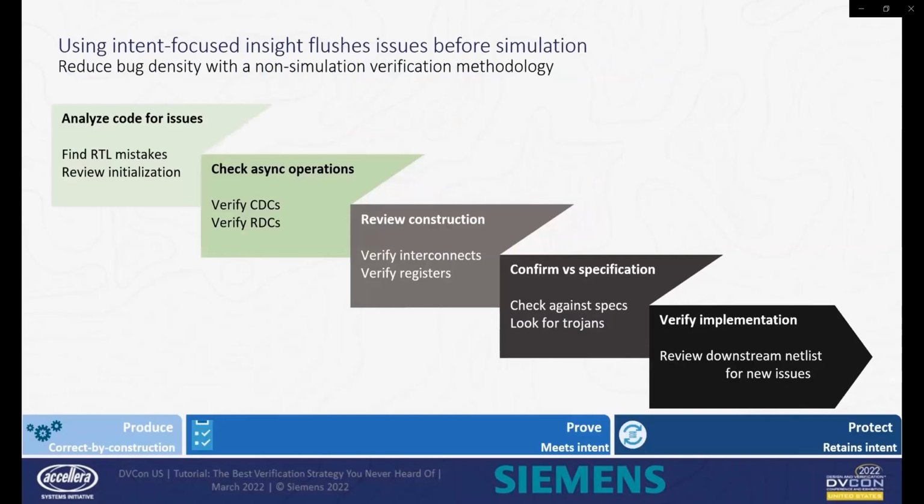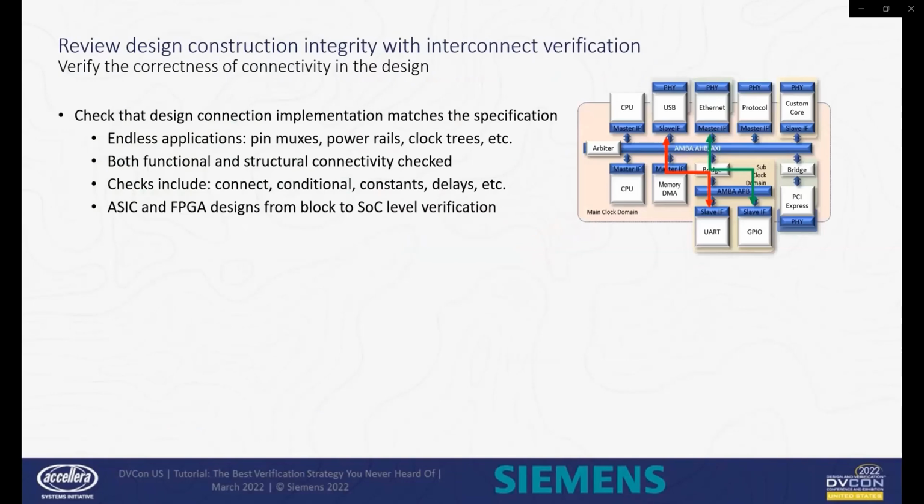Having now discussed the asynchronous operations, let's move on to consider how the capabilities of an intent-focused verification methodology might help eliminate construction bugs in the design before they're caught in simulation. One type of construction issue that might occur is an interconnect issue. Today's SoC designs have a high number of connections. Most chips are pin limited and thus require a pin mux to share pins with various functions. There are various other connections, from power to control to clock and reset trees, to name a few.